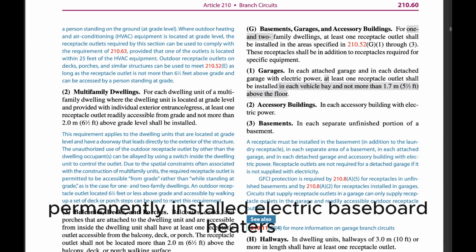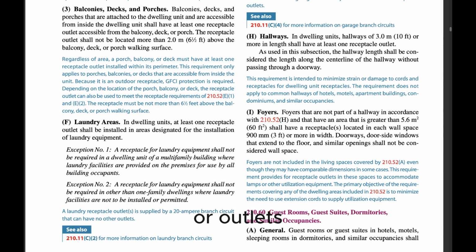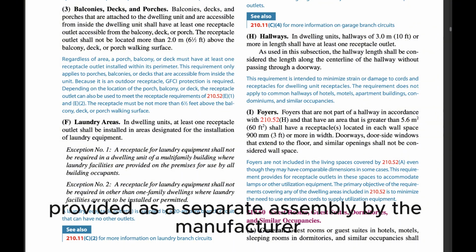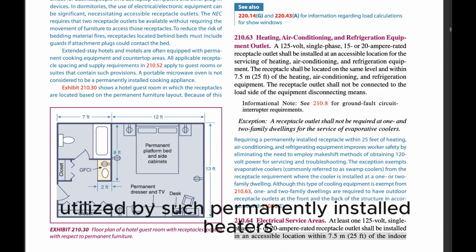Permanently installed electric baseboard heaters equipped with factory-installed receptacle outlets, or outlets provided as a separate assembly by the manufacturer, shall be permitted as the required outlet or outlets for the wall space utilized by such permanently installed heaters.